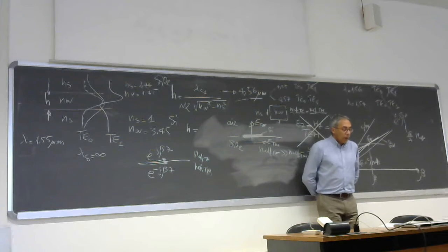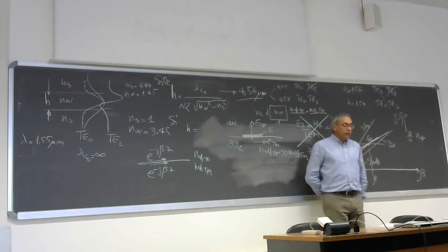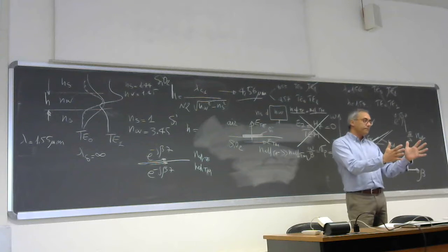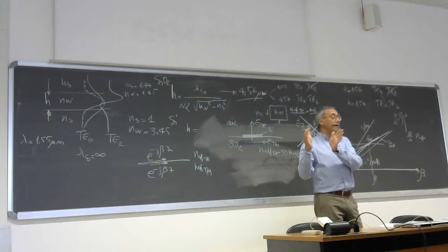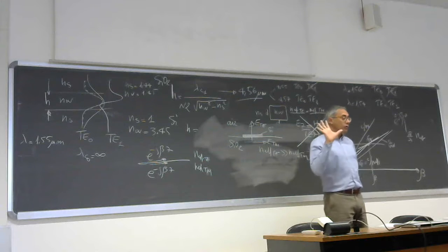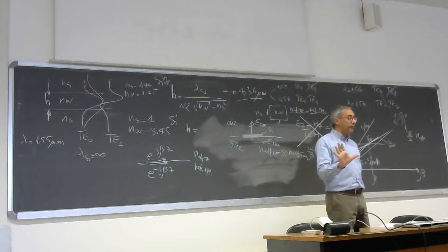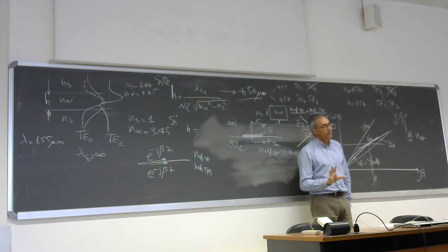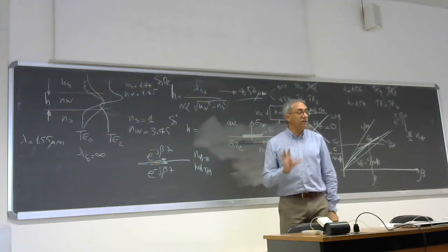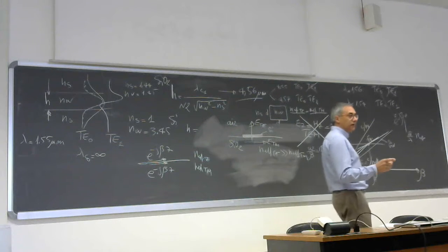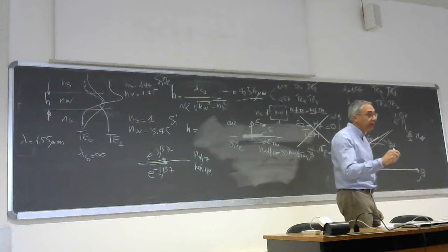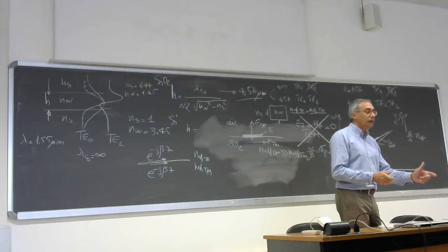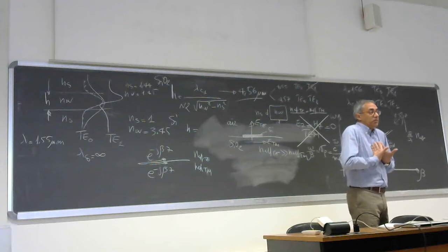It is clear that you can do signal processing in the optical domain or in the electrical domain. If you want to do the signal processing in the electrical domain, you have to access the phase. And the only way to access the phase is to do a coherent detection. So you see, we are talking about a very specific device, a receiver.